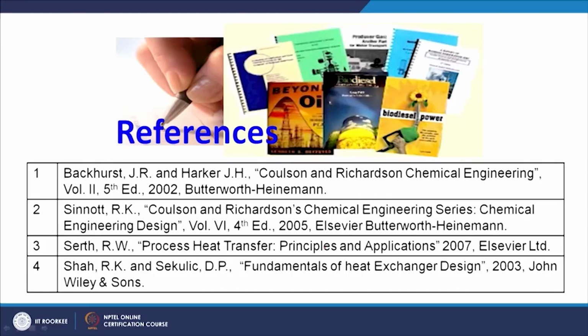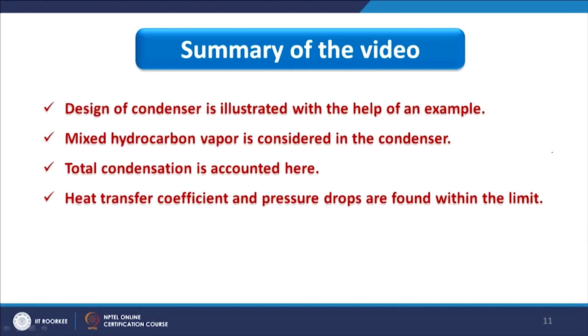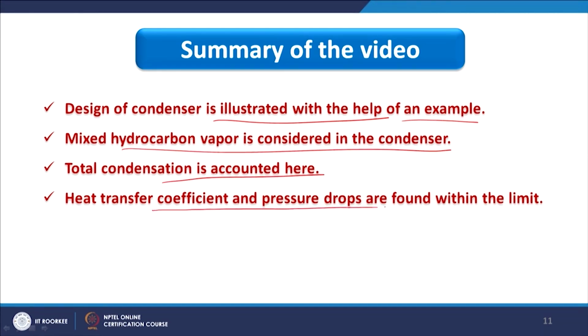and here I am having some of the references, and now I am summarizing this video as design of condenser is illustrated with the help of an example. Mixed hydrocarbon vapor is considered as a feed. Total condensation is accounted here. Heat transfer coefficient and pressure drops are found within the limit. And that is all for now.